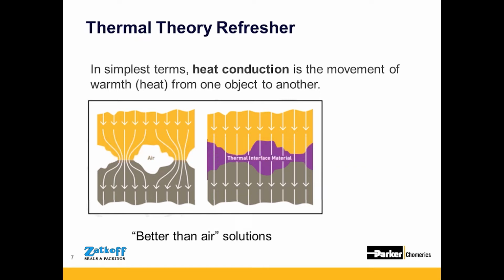Thermal interface materials are just that, materials meant to transfer heat at the interface between a heat generating component and a cooling feature. Heat generating components can be anything from semiconductors or batteries to large electronic assemblies, while heat sinks or housings or enclosures can serve as cooling features. TIMs use conduction to pull heat away, relying on contact between components to remove interstitial air gaps. Densely packed ceramic particles within silicone binders give TIMs excellent durability and thermal conductivity while ensuring electrical insulation and no concern of shorting electrical leads.